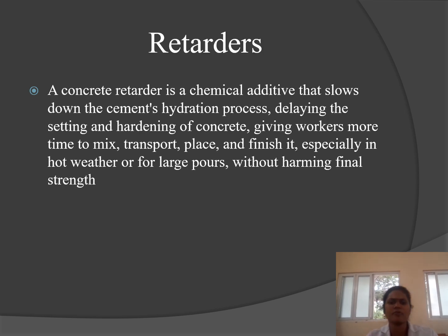Next is retarders. What is meant by retarders? A concrete retarder is a chemical additive that slows down the cement hydration process, delaying the setting and hardening of concrete. This gives workers more time to mix, transport, place and finish it, especially in hot weather or for large pours,